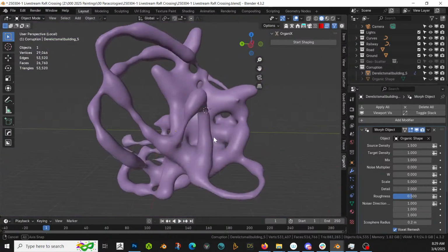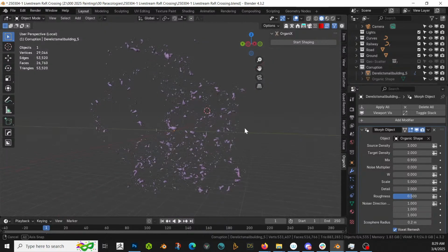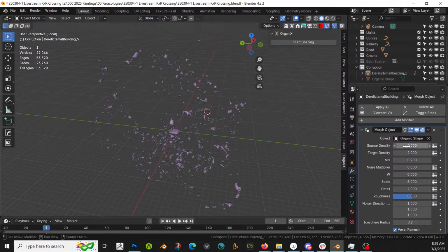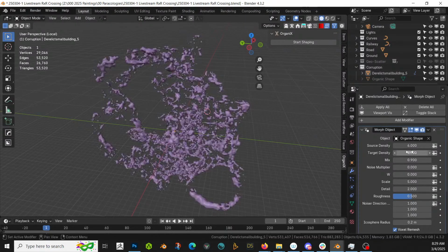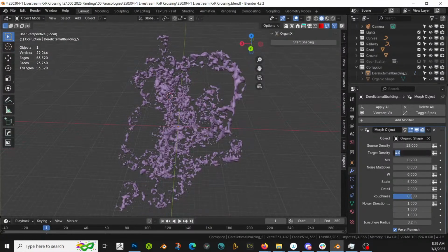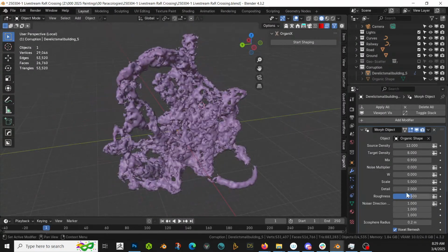That's interesting. It's because we didn't have that many source vertices. So take this up to 3 and 2, and a mix of 0.9. That's better, yeah. So let's double it. 6 and 4. We'll gradually go up until we get to where we want to be. 12 and 8. Yes. Okay, now we're getting somewhere. Mix 0.5.